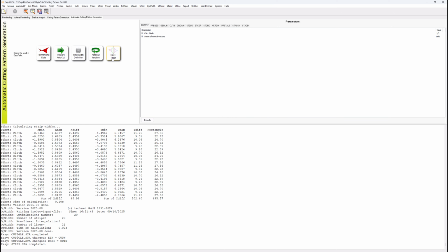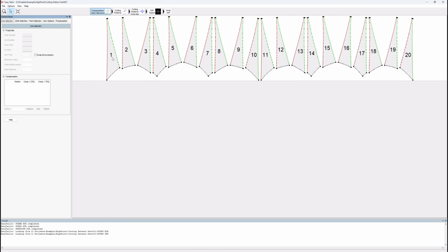This module opens in a separate window where the cutting patterns are displayed. The X and Y directions define the material orientation. Due to the twisted cutting elements, however, these do not run towards the high point, meaning that the prestress in the installed state does not follow the fiber direction.